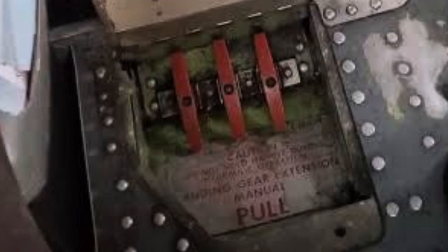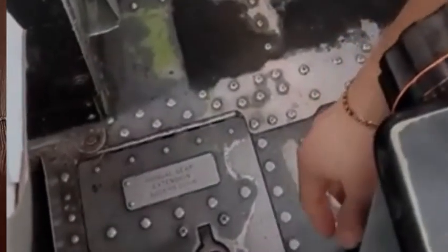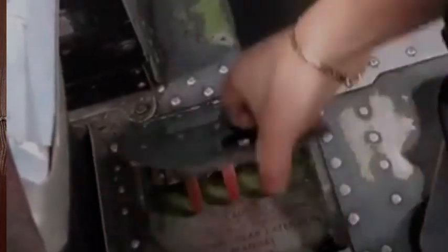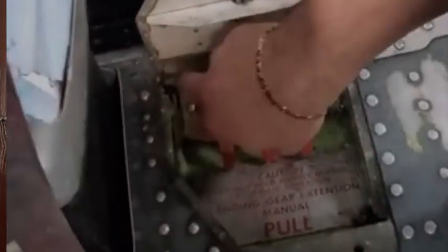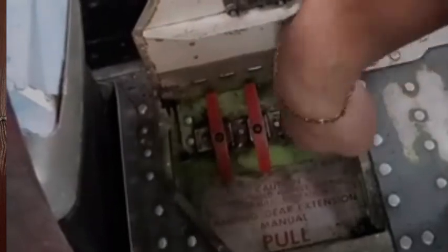Based on the non-normal checklist and procedures, we need hydraulic system A to be depressurized completely, and then we put the landing gear lever to the off position. Extending the center lever and cable up to the limit will disengage the uplock mechanism, and then the nose landing gear will free fall by its own weight and air load. It will come down, the downlock mechanism will automatically engage, and the nose landing gear is ready for landing.